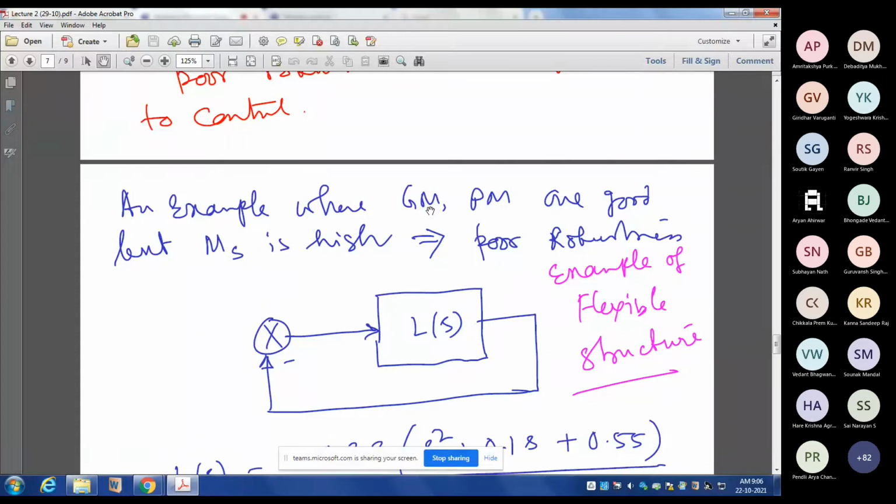Suppose your gain is 1, then plus 6 dB upper side gain margin means you can increase it up to 2, and minus 6 dB lower side gain margin means you can reduce the gain by a factor of 0.5, that is, down to 0.5. That's why plus minus 6 dB gain margin is considered a good or reasonable gain margin for a practical system.